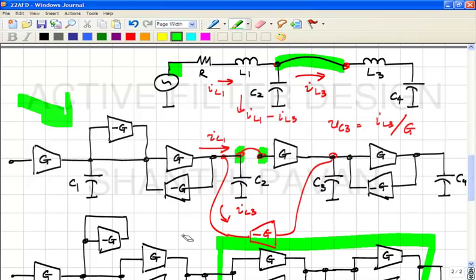Okay. Now, but there is a definite advantage to using a cascade of biquads in the realm of being practical, because it's very easy to debug a second order section, correct? Because how do you debug a second order section? In other words, let's say you designed your omega naught to be 2.2 megahertz and Q to be 2.